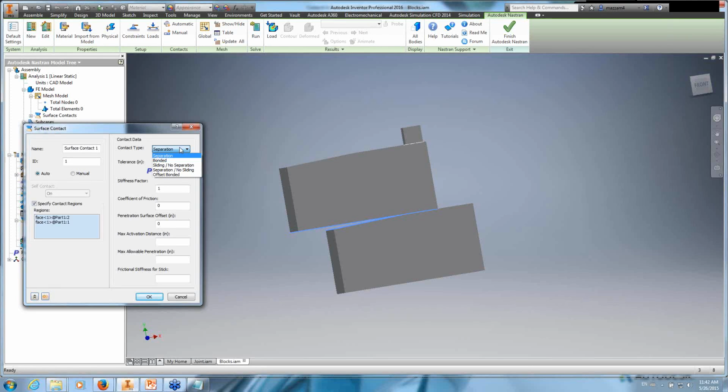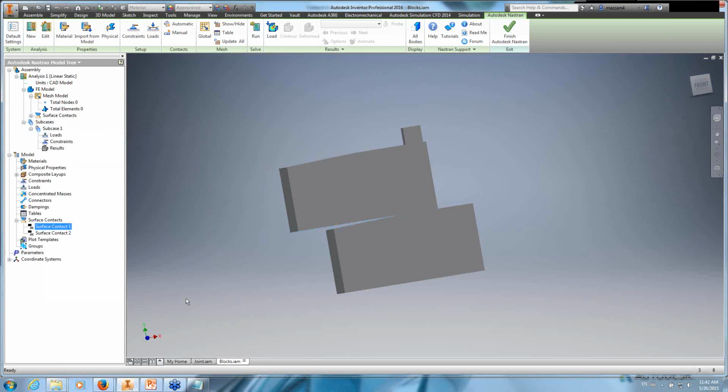We have another question here from Daniel. By default, the boxes are not considered one solid, and that's correct. This was brought in, I believe, Marwan, as an assembly. Each one's a separate part, so you'll need to define a physical property and then materials for each box. You can go in and define them separately as well. You could also, if you wanted to define them as shells, select the outer surfaces and then mesh those, and you'd have a shelled part instead of a solid part.